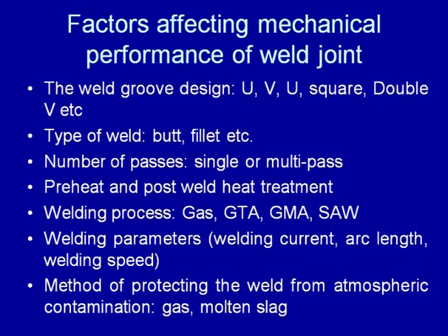Greater application of heat will deteriorate the mechanical performance of the weld joint, because higher heat input frequently causes a coarse grained structure in the heat affected zone and in the weld region, which in turn deteriorates the mechanical performance of the weld joint. So, the load carrying capacity of the weld joint will be decreased. Then the type of the weld.